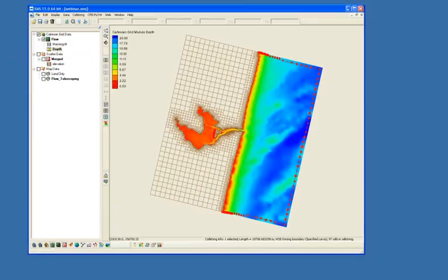Another way to do this would be to run it directly from the command prompt. And that's how we normally do it here. Because you're running within the SMS interface and it's monitoring everything that's written to that file and it's taking up memory, it may actually slow down the run of your actual simulation. And if you have multiple of these, you might not want to start an SMS version every time you want to run. You want to actually run these from the command prompt.